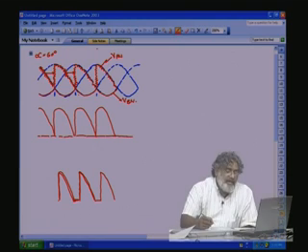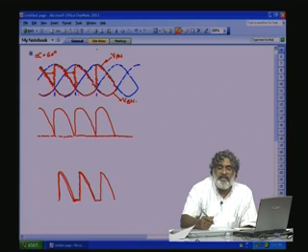That is, the current switch on and off are instantaneous, but due to the presence of line inductance in the AC supply, the transformer and the SCR circuitry will not permit instantaneous current change. Even though the thyristor can be instantaneously turned on and turned off, there will be a finite line inductance, transformer inductance. So a conducting limb cannot switch on or switch off the current instantaneously due to the finite inductance.